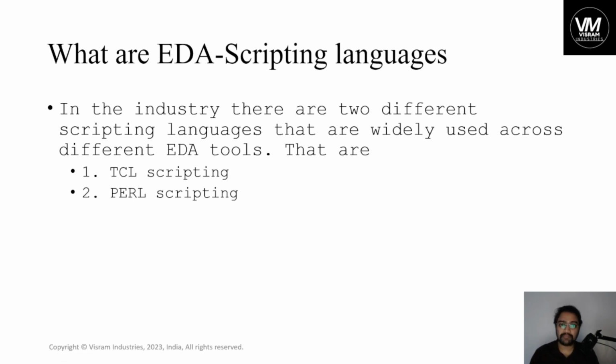VHDL or Verilog HDL is used to develop the architecture on the FPGA chip, and by using this VHDL file, and you take these input files, constraint files, .xdc file or .vhdl file, you can take all these files and embed them in the EDA tool. Now you should give some commands to the EDA tool, and those commands are written in the language called Tickle, tool command language. So TCL has a set of commands. In the previous lectures, we have also used report IP status, where we can see the license available for the IP. Commands like report timing, report IP status, all these are used to execute the EDA functionalities. So we are giving instructions to the EDA tool, not to the design. So now the EDA tool will be operated according to this set of Tickle commands.